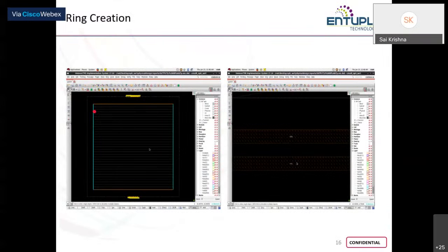Okay. So your rail will be all along these standard cell rows. Here, what you see is from the top view. Because you are looking from the top, you will see that metal 9, I mean the highest and the lowest metals, will be overlapping. But actually there will be a distance between them, a height gap. So using vias, you will connect them. You will connect your rings and strips to your rails.